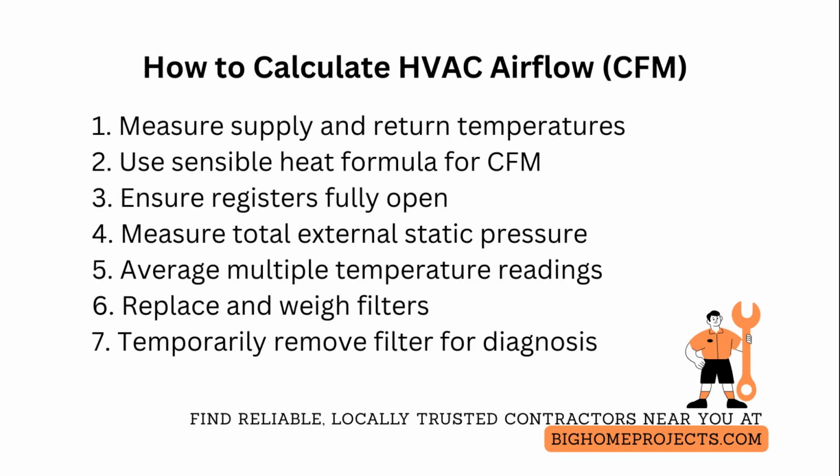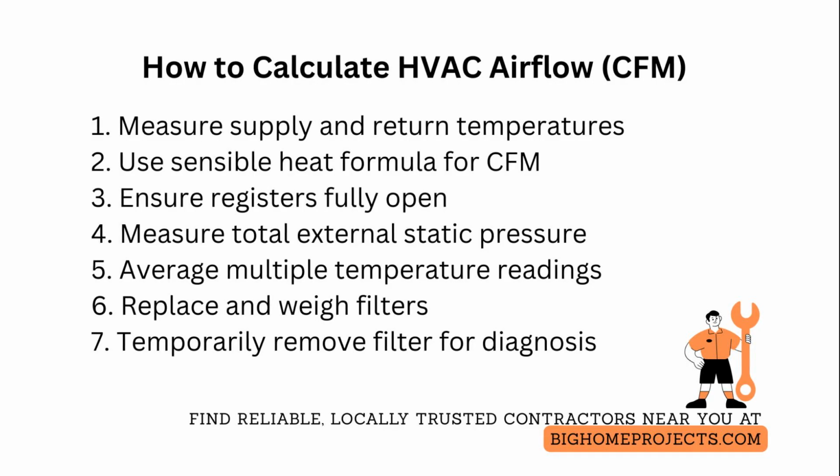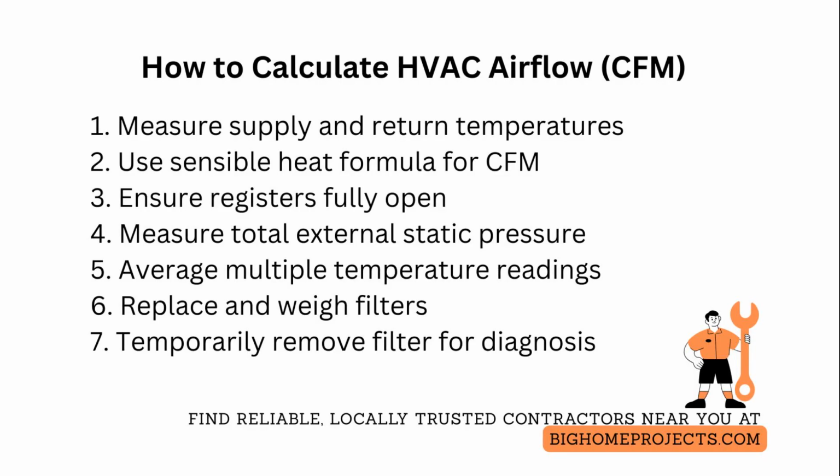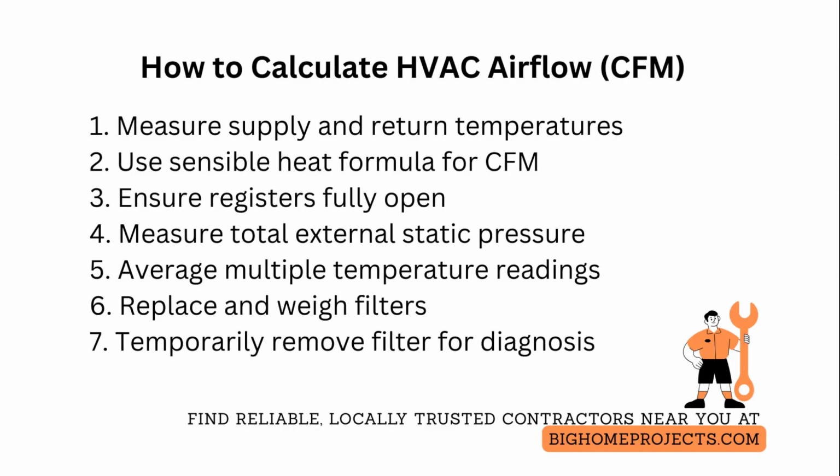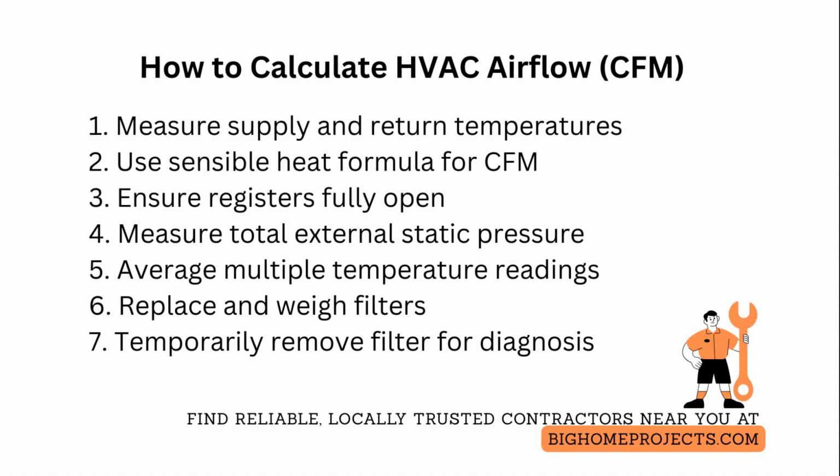If you suspect return restriction, temporarily remove the HVAC filter and measure the change in static pressure and CFM. Note that this is diagnostic only and run only briefly to avoid system damage. Use a pitot tube or calibrated capture hood for spot verification when accessible. Cross-check hood-derived CFM against temperature rise-derived CFM to validate your methodology. Document every measurement, time of day, and blower speed setting so future troubleshooting can compare apples to apples.